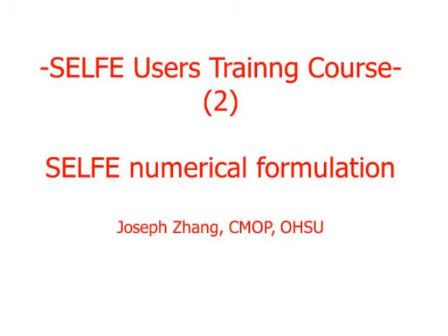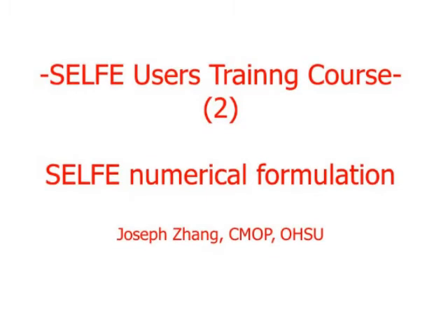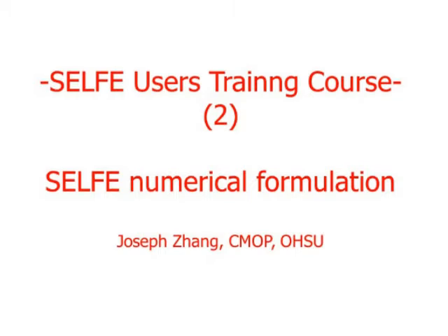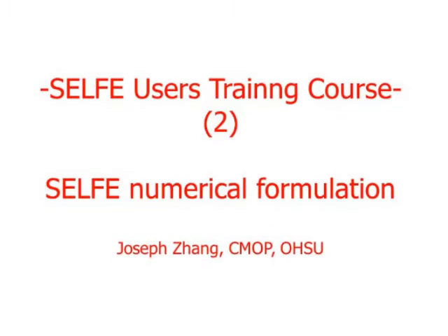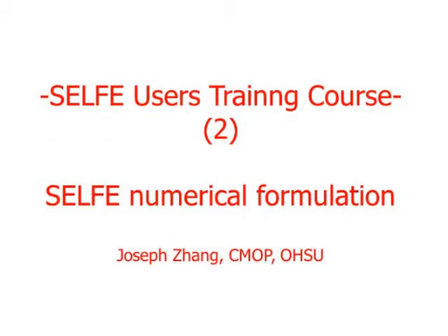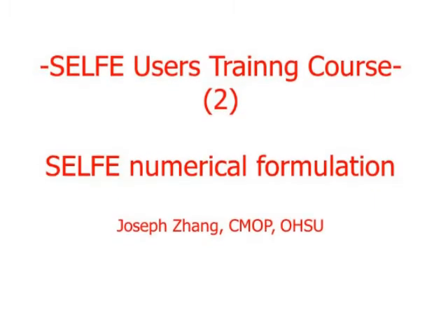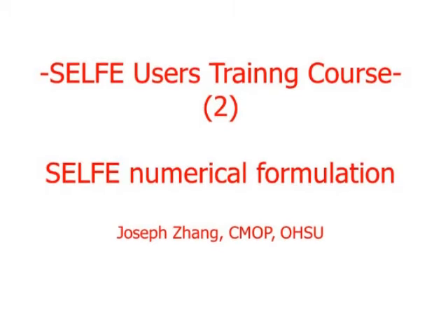So this is the Courant number condition, Vi over the summation of outgoing fluxes. This applies to a particular prism. Of course, you have to make sure this condition is satisfied for all prisms. So the final time step you can use is the minimum of all the allowable time steps calculated from this Courant number condition.